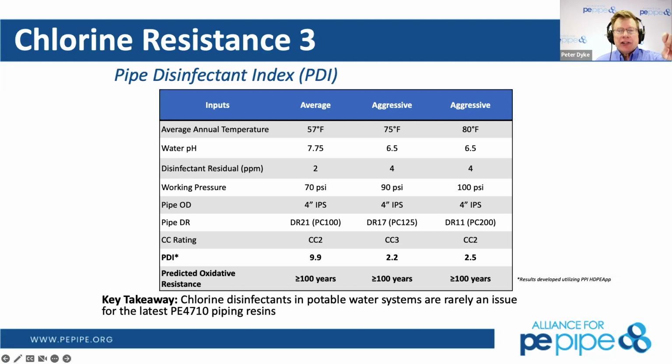We also had a person, Dusty, ask the question about chlorine dioxide. What is our recommendation if a utility is using chlorine dioxide as a secondary disinfectant? And that's a big distinguishing factor here. So secondary versus primary. Primary inside the water treatment plant, chlorine dioxide is completely okay just because it is consumed very quickly in that process. There's not a lot of trace or any trace usually of chlorine dioxide once it hits the pipelines. But if you are using it for secondary disinfecting, we're not recommending polyethylene. If you have something that is maybe like a closed loop system, part of your process of the water processing plant, maybe we can work with it.